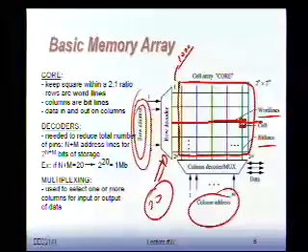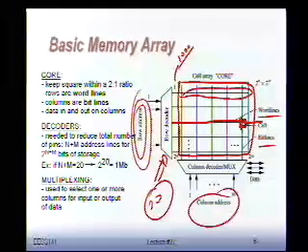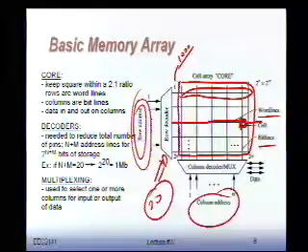Okay? Similarly, once I select a certain cell to read, I'm going to read out the whole row in one shot. So suppose I want to do a read operation or write operation. What we're going to do is read this whole row in one shot. So I get 1000 bits coming to the output, if I have 1000 by 1000. So I get one word line going high, I enable one row, all those bits come out.